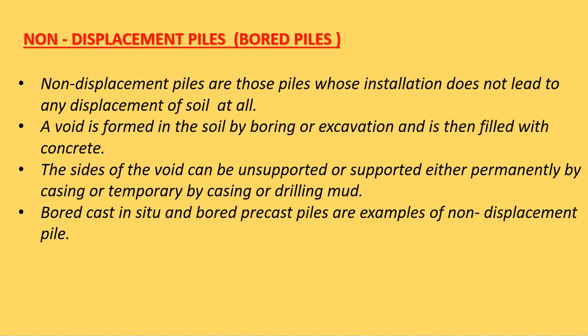Non-displacement piles. Non-displacement piles are those piles whose installation does not lead to any displacement of soil at all. A void is formed in the soil by boring or excavation and is then filled with concrete. The sides of the void can be unsupported or supported either permanently by casing or temporarily by casing or drilling mud. Bored cast in situ and bored precast piles are examples of non-displacement piles.